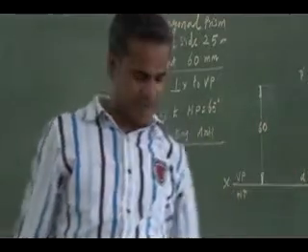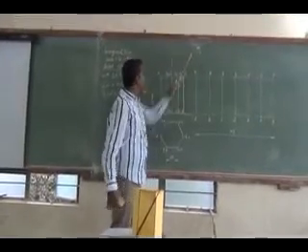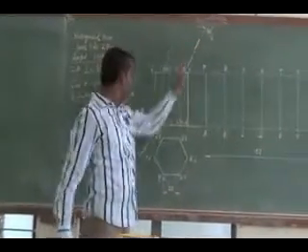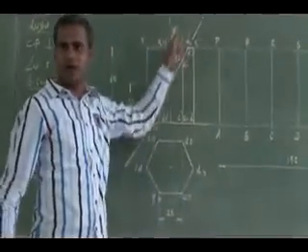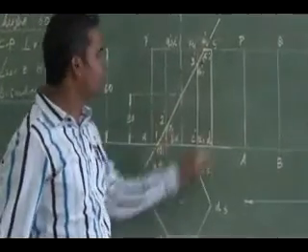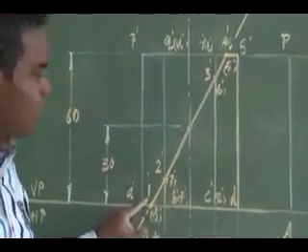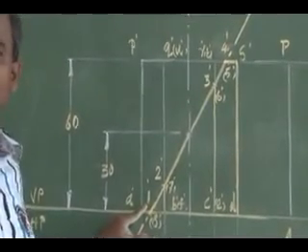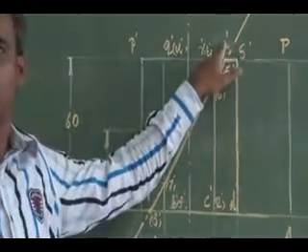So quickly you represent the cutting plane. You represent it on VP, right? So it cuts at a 65-degree inclination to HP. So if you represent the cutting plane, it cuts both the bases, right? So on the base I will get 2 cutting points, and it cuts 4 vertical edges, right? So starting from here, bottom, I can give the cutting points for visible cutting points. I can mark them 1, 2, 3 and 4 on the base.